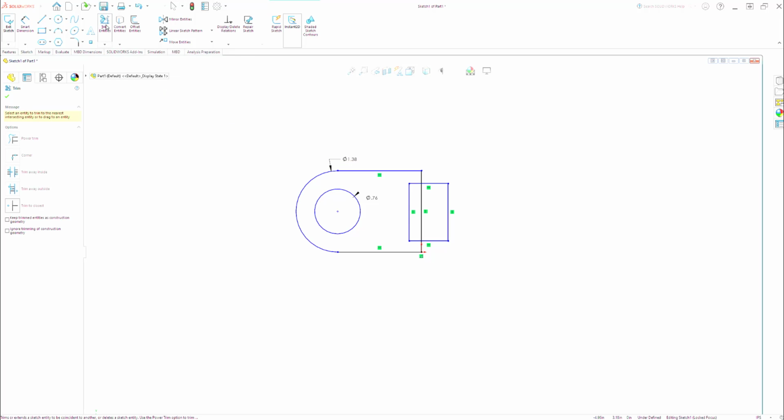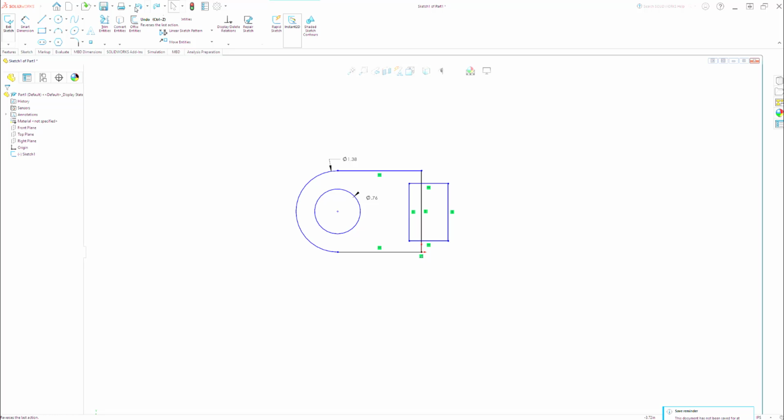Now, what happens if you nibble away something you don't want, or that you actually do want? Okay, so let's do that. Let's delete something that we actually want to save. So if I nibble here and go, oh man, I really wanted to save that. Well, if you remember, we've got that undo option up here, and it reverses the last action that we did. So I hit undo, and guess what? It gets rid of the trim command. It reverses the action of the trim command and eliminates it. So that undo is a perfect way to fix things when they go awry.